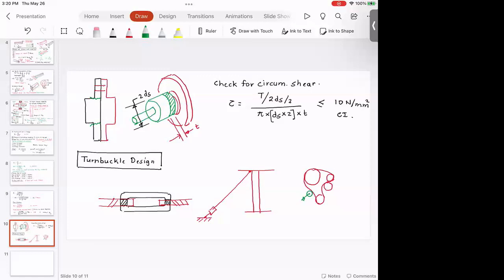Why does it need to have a pre-tension? Because please try to understand, this belt is going to rotate at high speed, which means there are going to be centrifugal forces that would naturally try to throw the belt out. So we need a pre-tensioner that will make sure that this belt will conform to the motion profile, stay on these pulleys and continue to transmit power from the crankshaft to the air conditioning compressor, then the alternator and the fan belt.